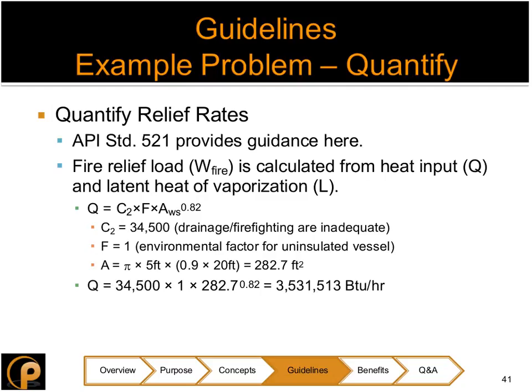Thank you. Every day there are changes taking place in owner-operator facilities. How does an owner-operator stay apprised of these changes and how they are affecting the relief system? The way to do that is with a very healthy management of change, or MOC, system. A very healthy MOC system will help everybody involved with changes going on in the plant recognize when something is going to affect the pressure relief system of any given system.